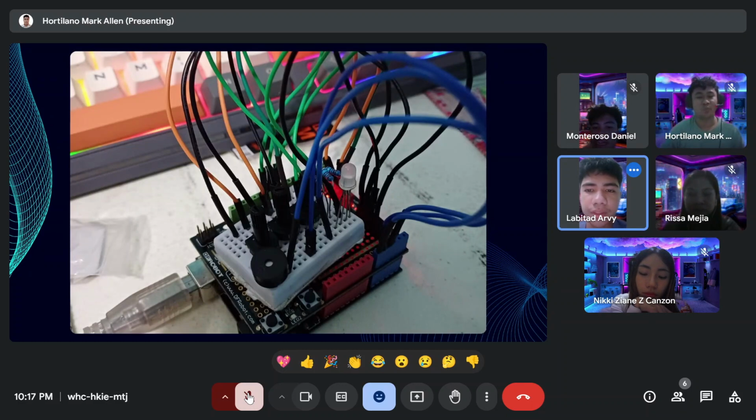One outer pin connects to GND and the other outer pin connects to 5V. Potentiometer 3, or blue: the middle pin connects to analog pin 2 on the Arduino. One outer pin connects to GND and the other outer pin connects to 5V.